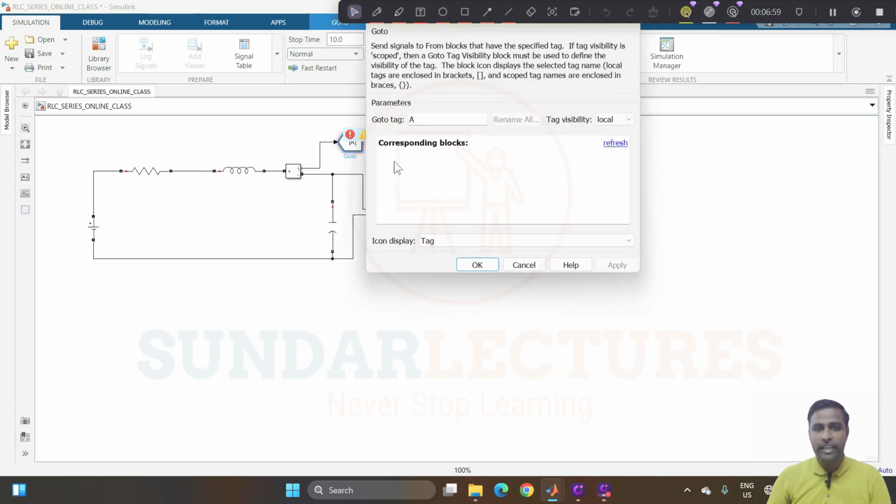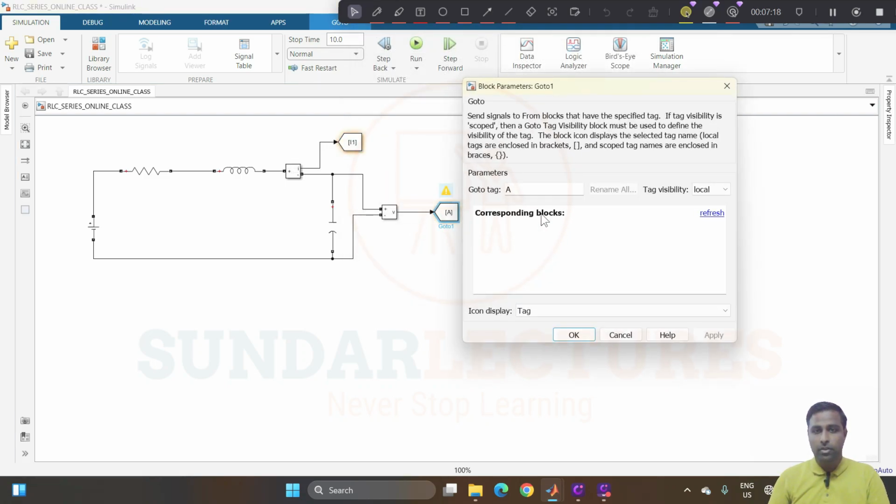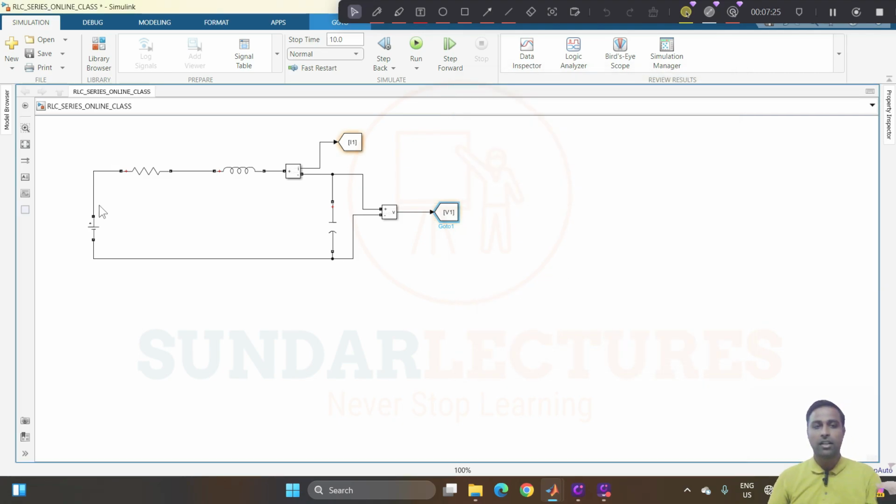Now go inside this, double tap on this, you have to change the value to I1 because we are going to create three circuits. So first what you do, create I1, go to tag, value is I1 here. This is I1, circuit current number 1, and then go here, then put it as V1, voltage number 1, OK, that's all. This is the circuit now.